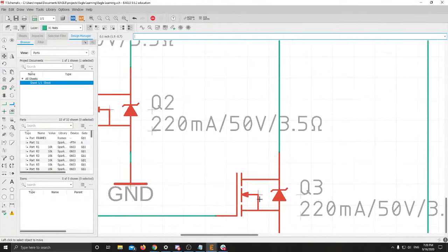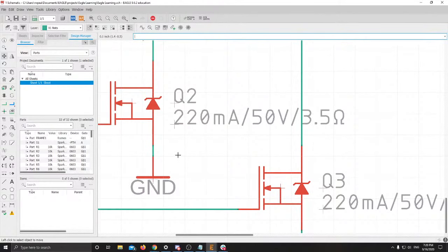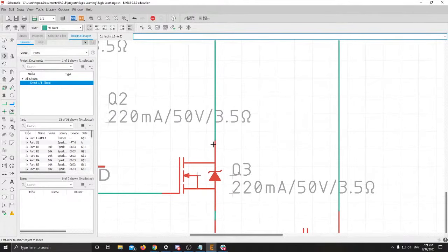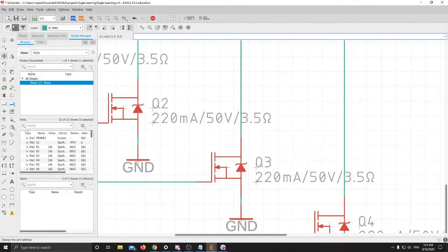I hope that makes sense, but basically everything that you do in Eagle has to line up with the grid, sometimes relative to the origin, but sometimes the other parts don't. And if you have a net that's a little bit off, it'll figure it out. So if this were to not be aligned with the grid, it'll snap it to it for me, but it can be difficult to deal with sometimes, so it's usually best to change the grid size as you need.